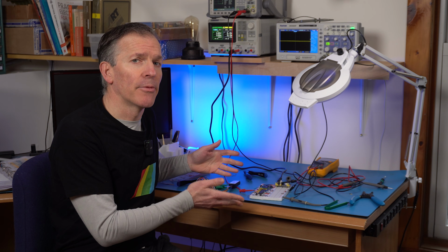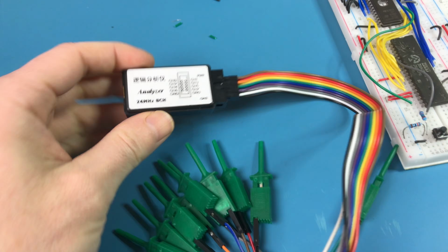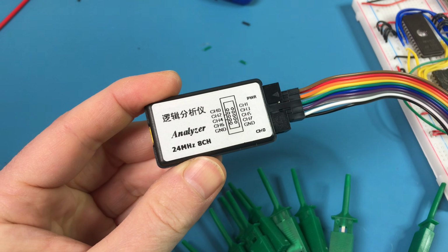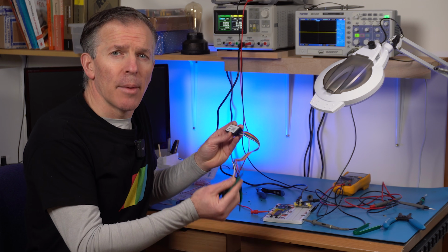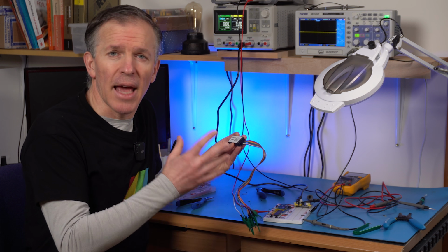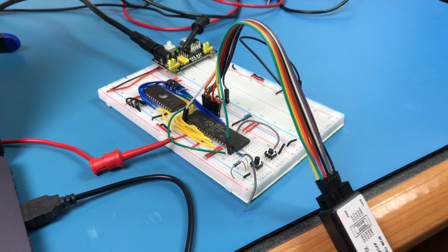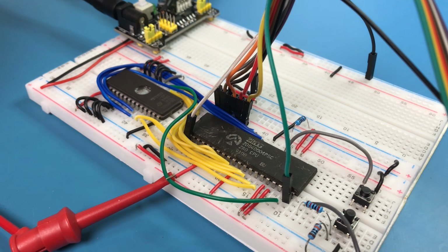This would be a perfect job for a good logic analyzer. And all I have is this cheap one, which the cheap part doesn't really matter as far as frequency because it's running really slowly, but it only has 8 channels. So I'm going to hook up one of them to IORQ and then the other 7 to the middle of the address bus, maybe between A5 and A11. That way we see part of the lower half and part of the upper half.